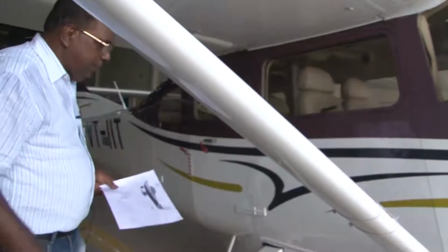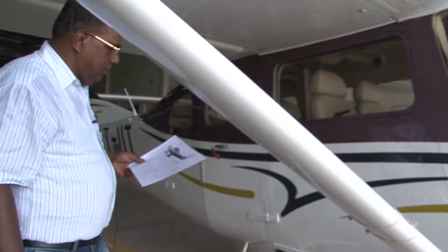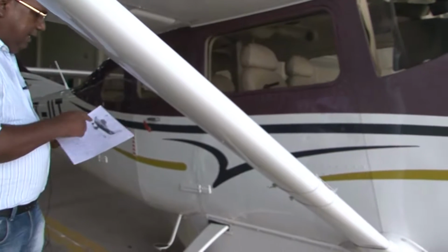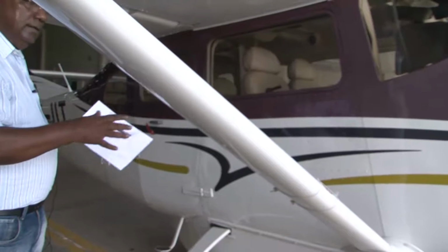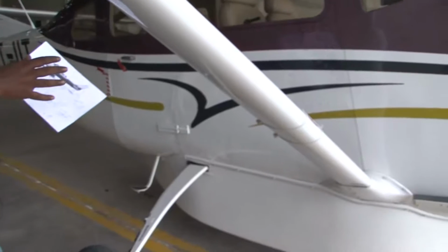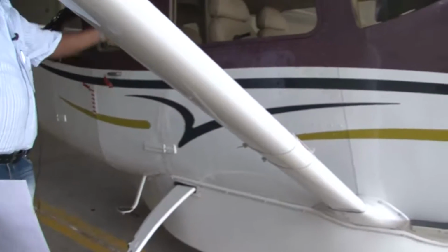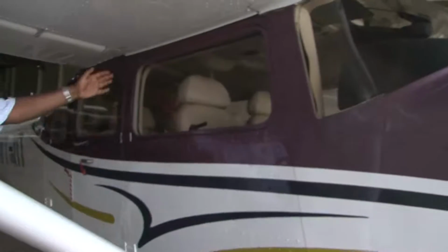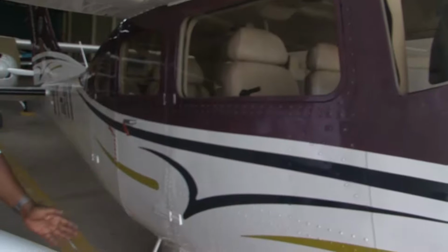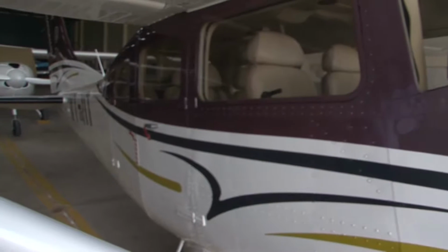And if you see the dimension here, this CG is roughly around 8.5 feet for most forward, and the landing gear is around 9 feet. Right? Okay. These are rough numbers. So what is being conveyed is you ensure that the CG is first of all near here where the people are sitting, the cockpit, etc., and that CG location should be a little ahead of the rear landing gear. Okay. So that also makes sense for us.